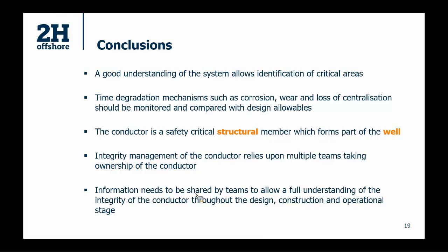The way I would define a conductor is that it's a safety critical structural member which forms part of the well, and it's because of the complex role of the conductor that it makes managing the integrity a little bit harder maybe than some other components, because it requires multiple different teams working together and sharing information to fully manage the integrity of the conductor. And that integrity management should be done throughout the life of the system. So it needs to be a focus at design stage, and then needs to be a focus during construction, and then throughout the operational life.